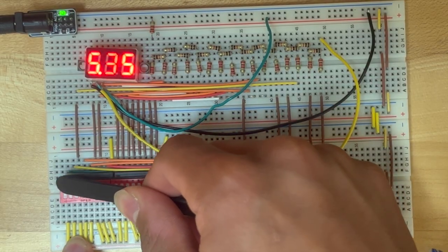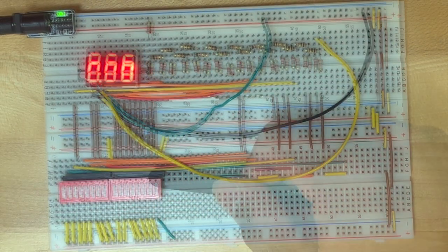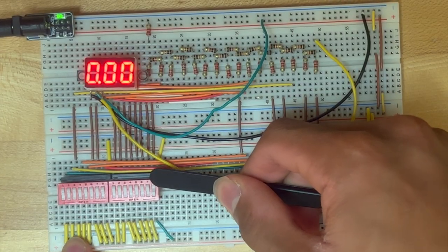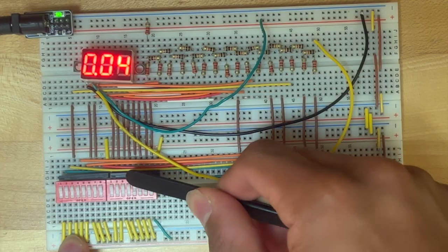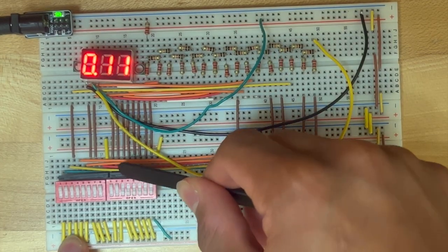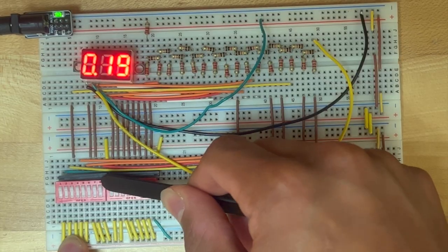As you may notice, for the first 8 bits, nothing really goes up in the voltmeter. This is due to the fact that their contributions are so low, 2 to the negative 16th, that the 3-digit voltmeter cannot display this.